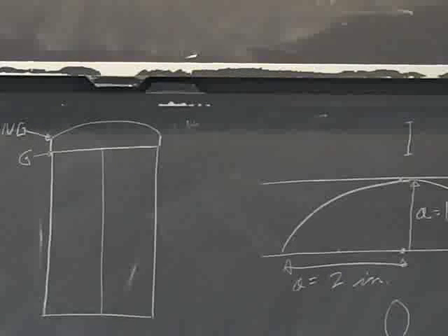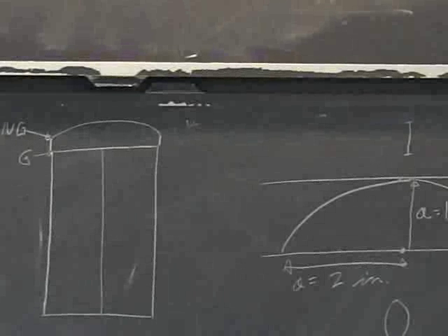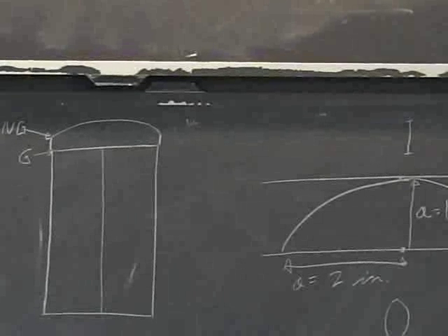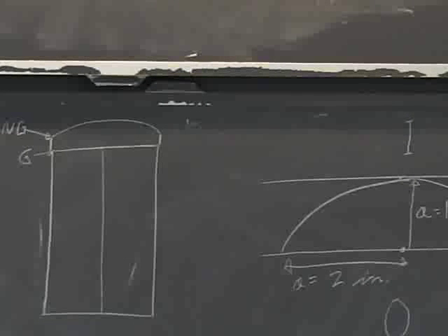To evaluate Q, you have to decide a stress level. So I put 80% of yield, thinking that I'm not going to grow the whole tank yet. So I'm below the yield strength for the pressure vessel. If you have catastrophic conditions, sometimes the ratio could be 1. You could be at yield.